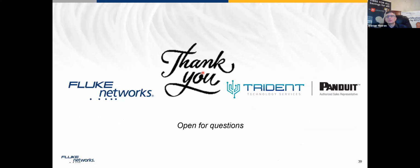That's it. That was a little bit around our industrial Ethernet, so very close to enterprise Ethernet, but with these new parameters, MICE, different connectors, you have to measure end to end. Take into account that temperature could have an influence on the length that you can still use on your cabling.